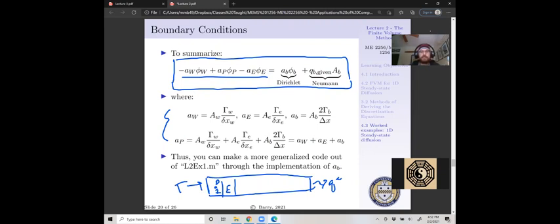If you had two fluxes, would you need to specify your initial conditions? Yeah. So two fluxes. What you'd have to be incredibly careful of is you're really upholding the conservation of energy. For definitely a steady state solver, energy has to be conserved. So if we think about this as a bar of copper and it was perfectly insulated and there are no source terms, your flux in has to be equal to your flux out.